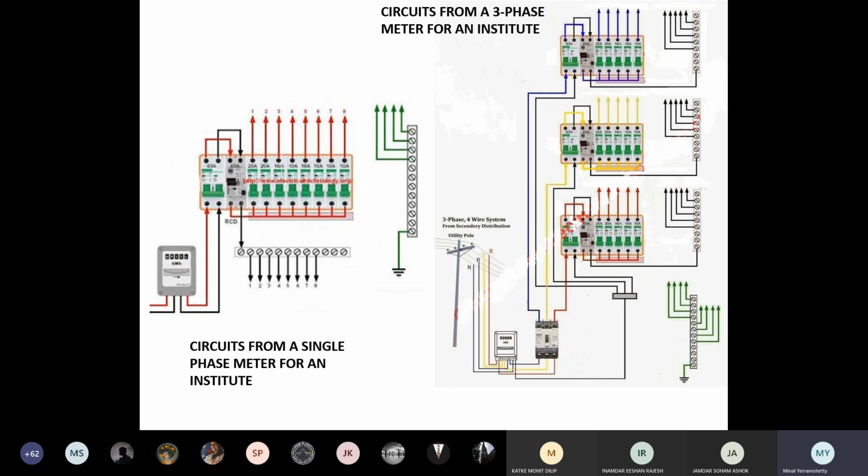So generally we keep the AC plug point different, near the AC. Why? Because the line becomes shorter. I save on lines, I save on the wires, because those are 15 ampere. So I will generally have it nearby. Now from there, the bulk of the line is taken to the MDB. So the circuit basically ends at the MDB.